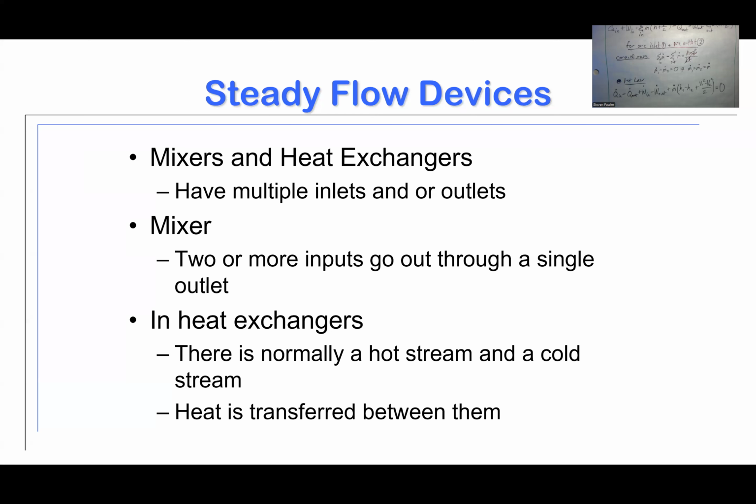And that's going to cool a hot stream of radiator fluid that gets returned back to the engine. And that's how we get the excess heat out of the engine in an internal combustion engine in a modern car. So there you've got a hot stream of radiator fluid, you've got a cold stream of air coming through, and they never actually mix. You're just simply going to transfer heat between them, right?